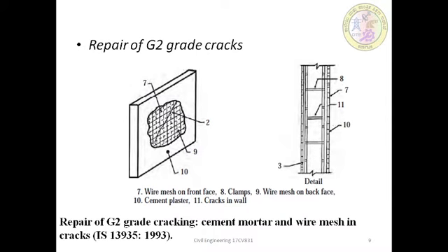In case of much larger cracks, the units become loose and the repairing process has to be more extensive than injection. In that case, the defined process is to remove the cracked unit and insert a new unit in rich mortar, or use steel bars or stitching dogs to fill the voids. The same procedures can be continued on the opposite side of the wall if necessary. This figure shows how the repair procedure is to be carried out.